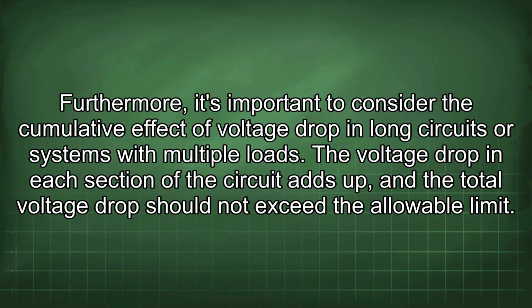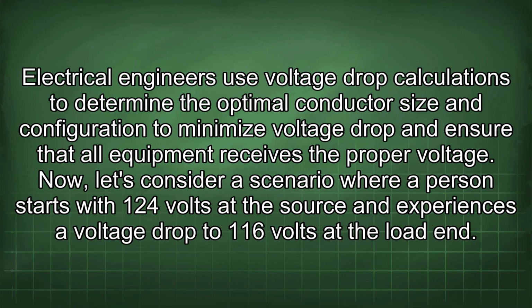Furthermore, it's important to consider the cumulative effect of voltage drop in long circuits or systems with multiple loads. The voltage drop in each section of the circuit adds up, and the total voltage drop should not exceed the allowable limit. Electrical engineers use voltage drop calculations to determine the optimal conductor size and configuration to minimize voltage drop and ensure that all equipment receives the proper voltage.